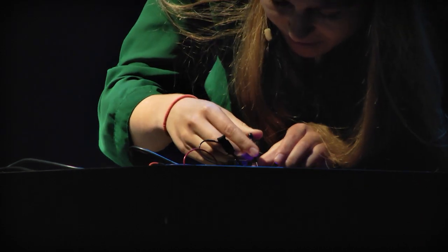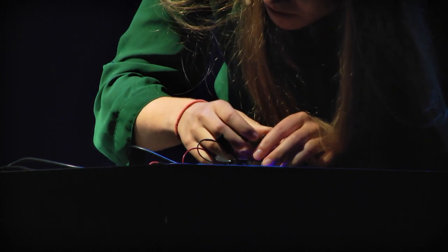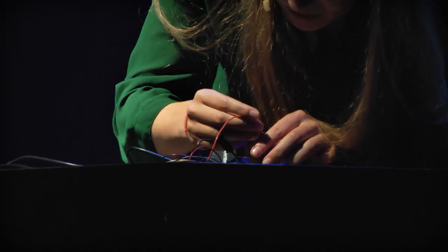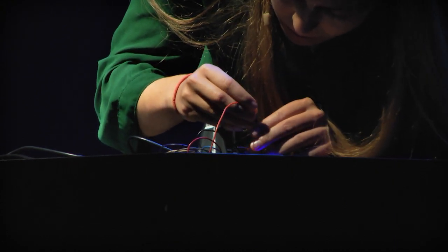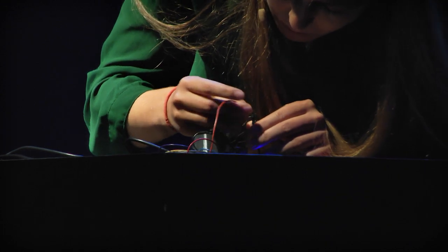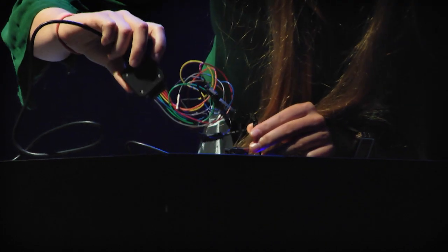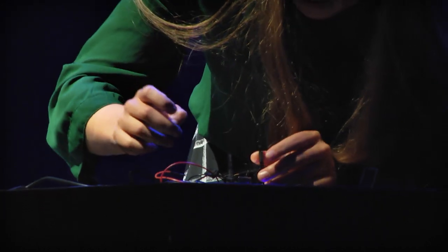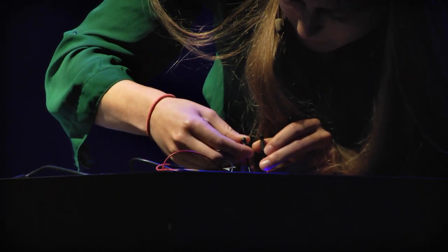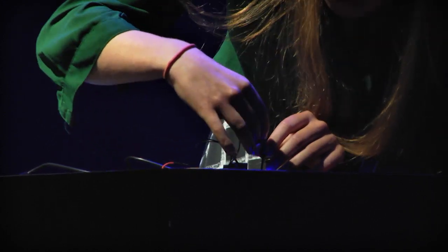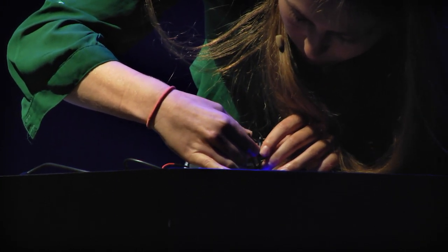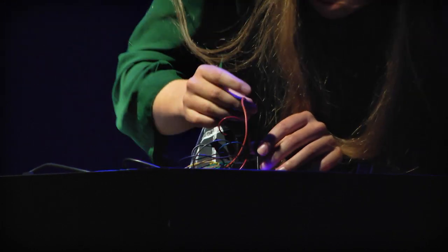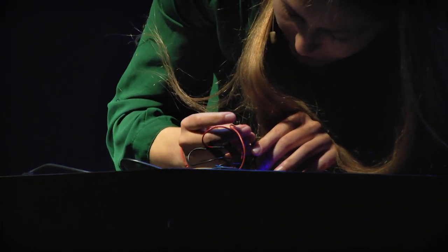RX and TX. So serial is a protocol that uses 2 wires, and the third wire is just ground, which you need in everything. By the way, the device that I'm hooking in is called a logic analyzer, and this is a really nice one. It's by this company called Saleae. What a logic analyzer does is it lets you have a look specifically at what the signals are saying on the pins. So you actually get to watch and record the messages that it's sending. And it even does stuff like interpret it, and I'll show you in a second.